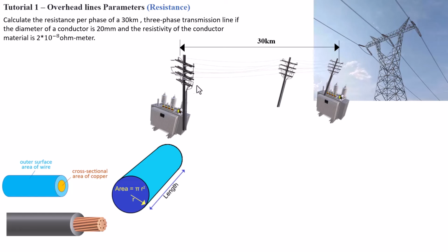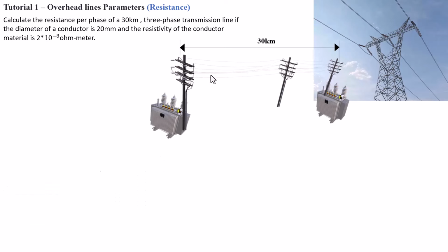However, there is something you have to understand here, that there is a trade-off. If your cables are too thick, the cost of installing them will also increase because you need much stronger structures to withstand the weight of those cables. If you make them smaller, then they can also dissipate more heat as the resistance will also increase. So you need to balance between larger cross-sectional area or diameter versus the strength of your structure. So that's basically what you need to know in a nutshell. But now let's get going with solving this particular problem here.